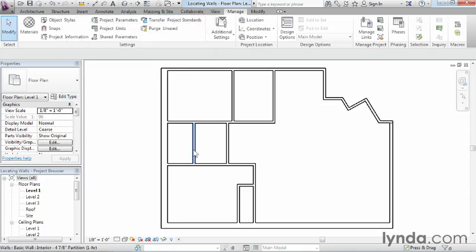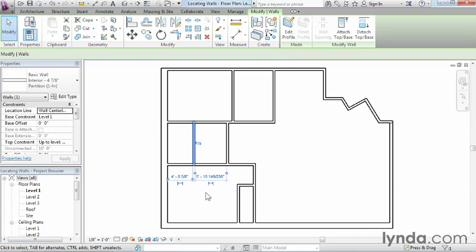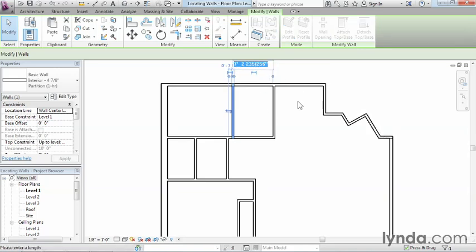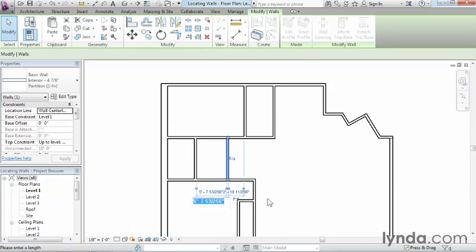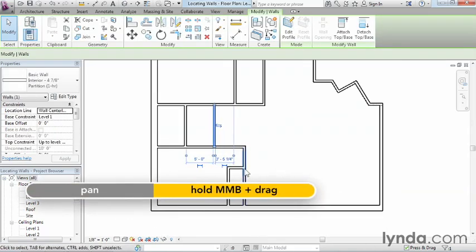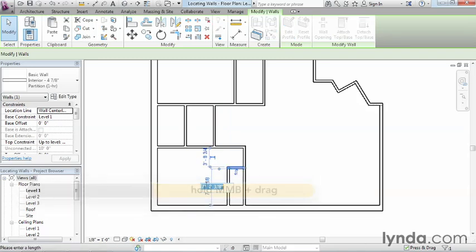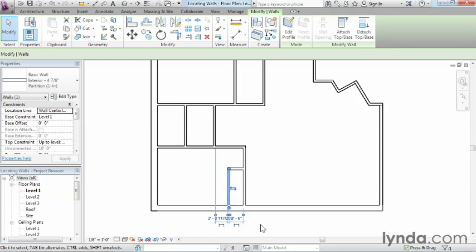When I click OK and I select the new wall, you'll now see the difference in behavior. The temporary dimensions are automatically going to the inside faces of the wall now instead of to the centers, which means I can go in and immediately change that number, and it's going to make these modifications move a little bit more quickly. These 2 bathrooms are both 5 feet. This one right here as well. And this closet here, I'll make that 7 feet. And I'll make this 2'6". Now remember, to do 2'6", you do 2 space 6, or you do 2 feet 6.